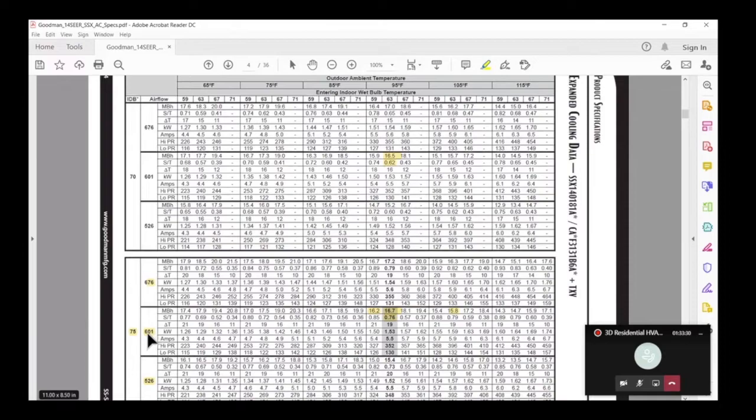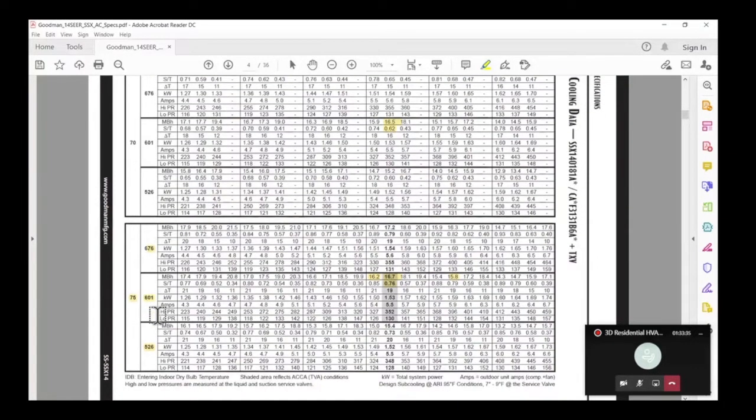So what if we go, instead of 601, let's go lower, because that's usually what happens. You undersize the ducts. So we want 600 CFM in order to get this number up here, or we're hoping to get that number. What if we undersize the ducts, and instead of getting 601, we get 526? We will be there, 15.4.